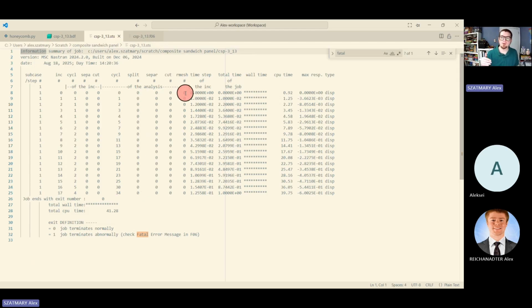And typically when we're doing nonlinear, the full load doesn't get applied immediately, it gets applied in increments, and more load gets gradually ramped up. That's more likely to give us a converged result. For a static scenario, we still have something called time, but it simply goes from 0 to 1. If we're at a time of 2.59e-1, so that's 0.26, we would have 0.26 of the final load being applied at that point.